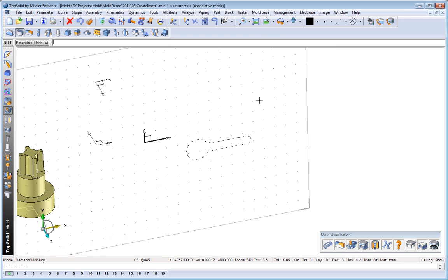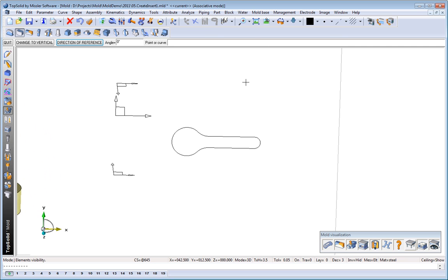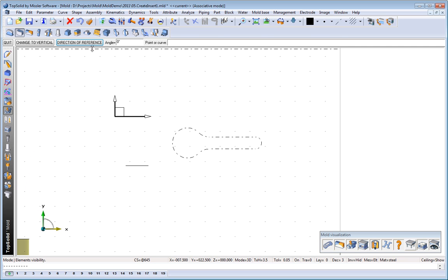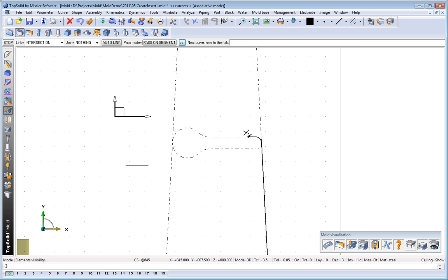the block, and then from here we'll add some simple sketch lines at an angle of 3 degrees per side to create some draft on the extremities of the part. You'll notice that we're snapping dynamically tangent to either edge. The final step here will be to select the segments that we want to use.